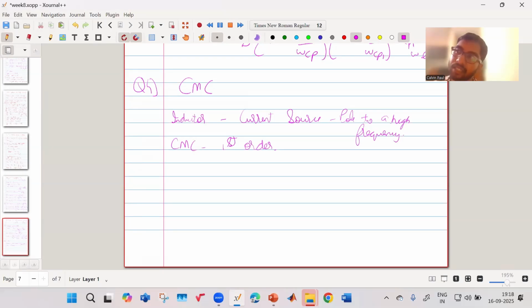It will give you the on the spot instantaneous information that your load current has changed, and since your load current has changed, your inductor current also has to change, something like that, right? So it is providing additional information which makes your whole loop less dependent on your value of R. That is the advantage of load current feed forward. Okay. And sir has also shown it in simulations as well.